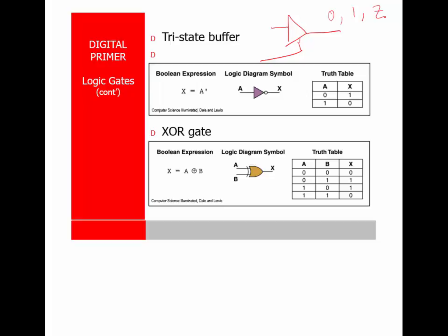We won't get into that today, but that output enable has to be active. Or there's another pin also called a chip select. Those are usually active low pins, and otherwise the output is going to be a high impedance. The reason is that in microprocessor systems, it's very, very common to connect multiple devices to the same wire.